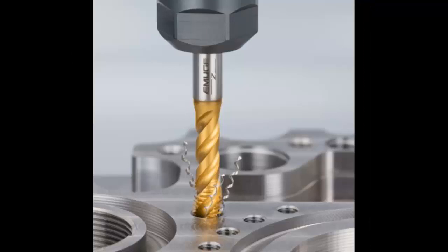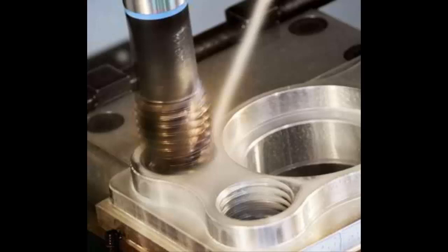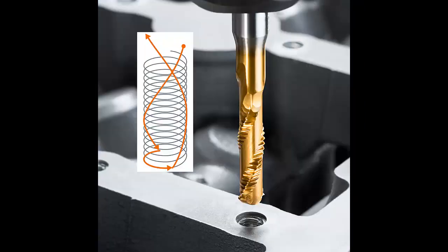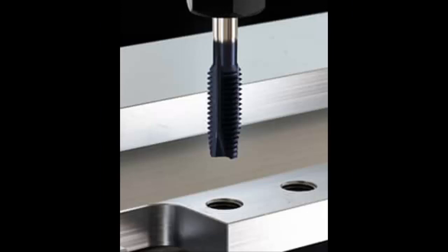Tapping is a common and useful manufacturing technique for threads of the workpiece. Tapping in manufacturing is the process of cutting a thread inside a hole, which needs to be drilled with a tap drill and chamfered at the end, used for screws or bolts being threaded into the hole. Tapping is a highly efficient, productive, economical and easy threading method, especially for small threads. It can also produce threads on nuts.